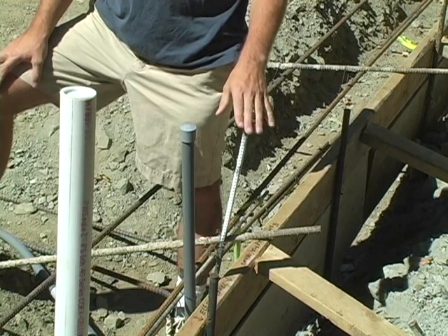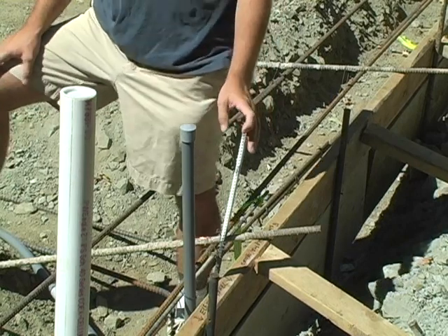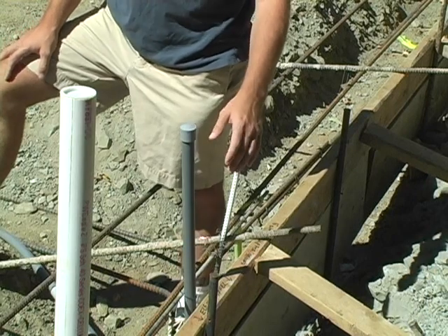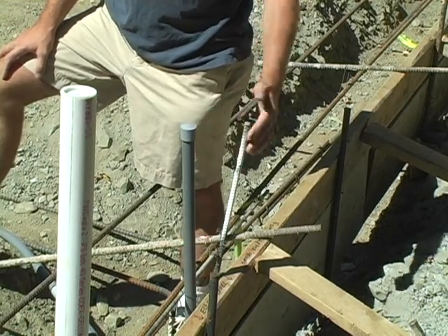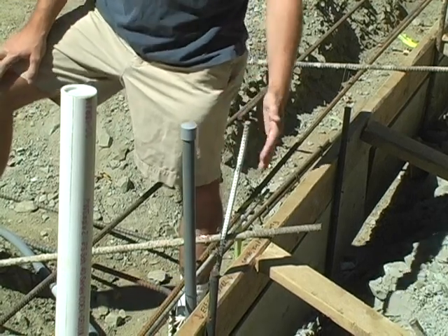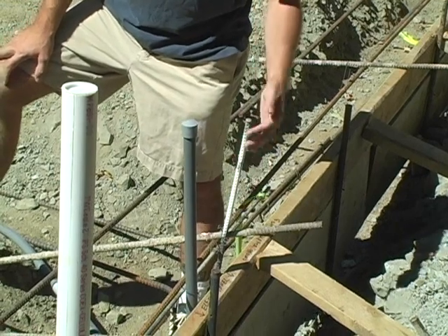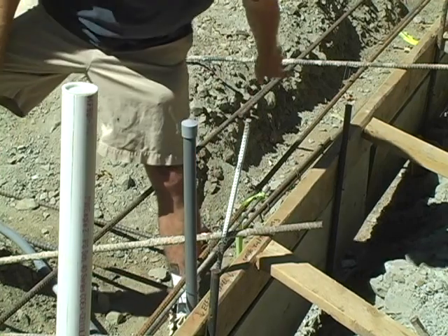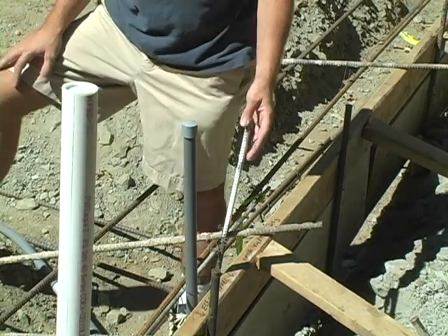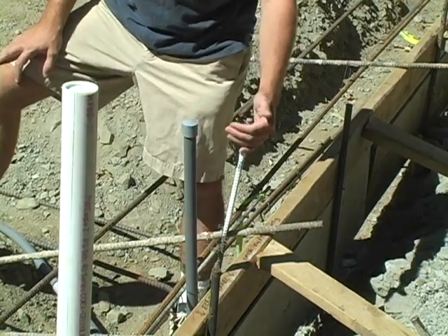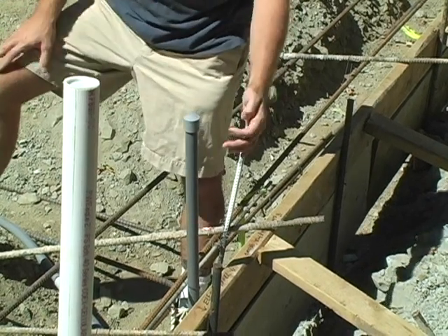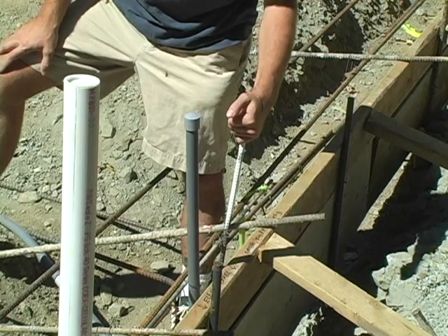Now when the electrical comes in, we need to know if we're going to have a service panel on the building. In this case, we have an electrical panel that'll be on this north-facing wall. And so in an area somewhere close to where that panel might go, we're going to have what's called a Ufer ground. This is basically a long piece of rebar. It's run down into the foundation and extends out. It's about a 20-foot piece all told. Now this piece is required to ground the electrical panel into the slab itself. So this needs to be in place before we pour our slab.